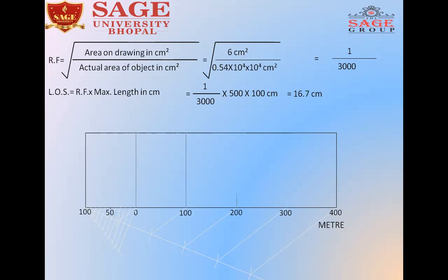Complete the rectangular box and erect a perpendicular line through each division. Now this is the completed rectangular box. In the first box, again you will take 10 divisions, because each part represents 10 meter. In the vertical line, you will take 1 part, which represents a single meter. This is the target of your problem.